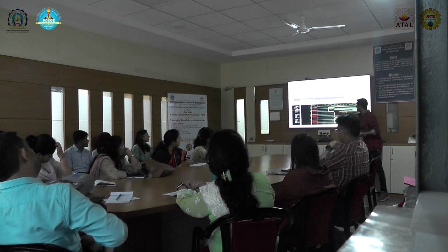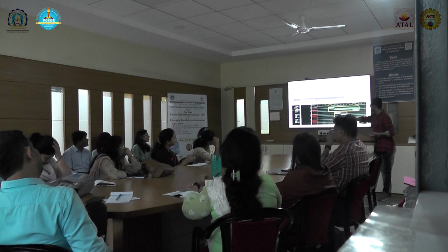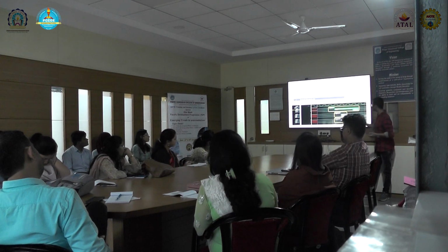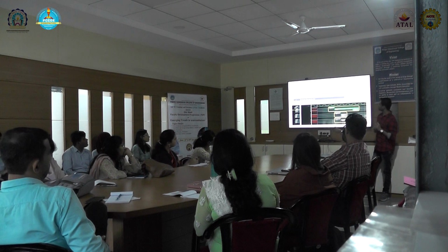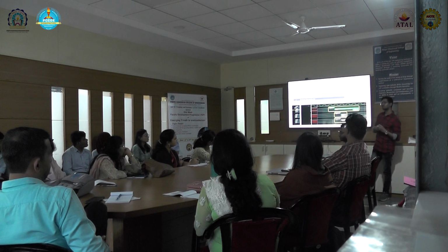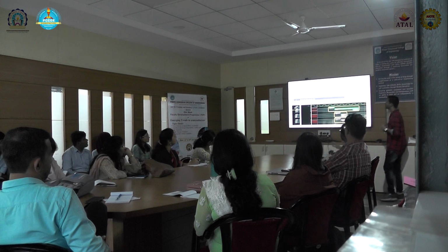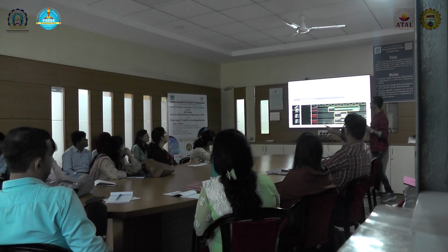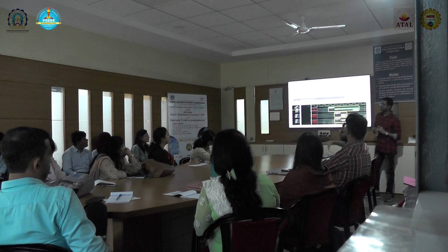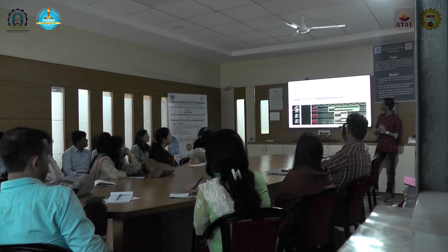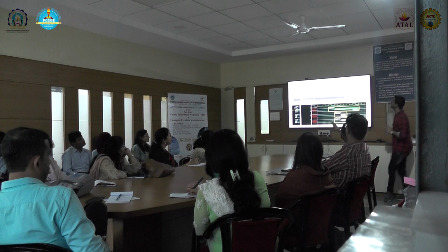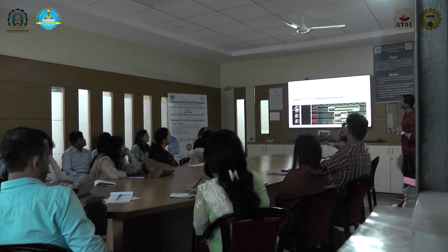Just a waveform: you sent the request, busy got high, then we got done, and when more dones come, done got high. This waveform is from the Synopsys FPV tool. If you see the above one, the property got true, so we can be sure that there is no scenario in which this case fails. We can be fully confident that the design which we wrote is behaving correctly.